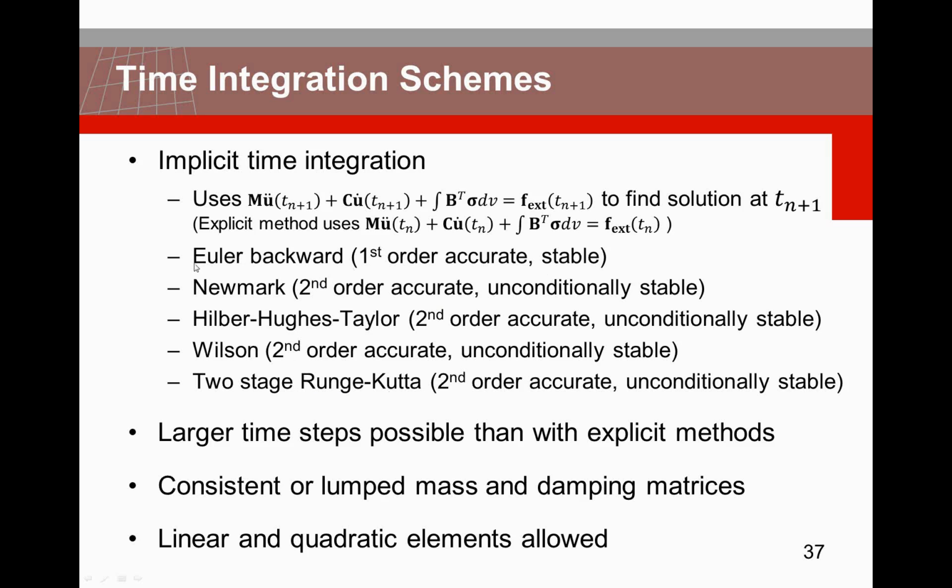What in practice means is that with Euler backward, which is the fastest method, to achieve the same accuracy as the other methods, you will need much smaller time steps, and then the benefit of the fast Euler backward method is lost due to the required smaller step sizes to get to the same accuracy in the solution. So yes, Euler backward is the fastest, but due to the accuracy and the smaller time steps needed, the methods do not matter so much.